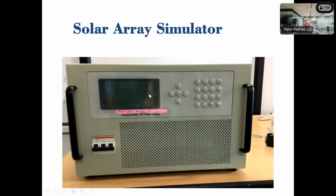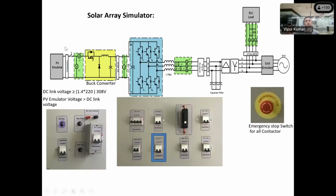Now this is the solar array simulator. This 5 kilowatt solar array simulator is basically a programmable DC source. Based on the software application, we make it simulate a solar array. So this is a DC power supply which will work as a solar array simulator, and it will mimic the behavior of the real solar panel. For lab purposes we usually use the solar array simulator to mimic the behavior of a solar PV array.